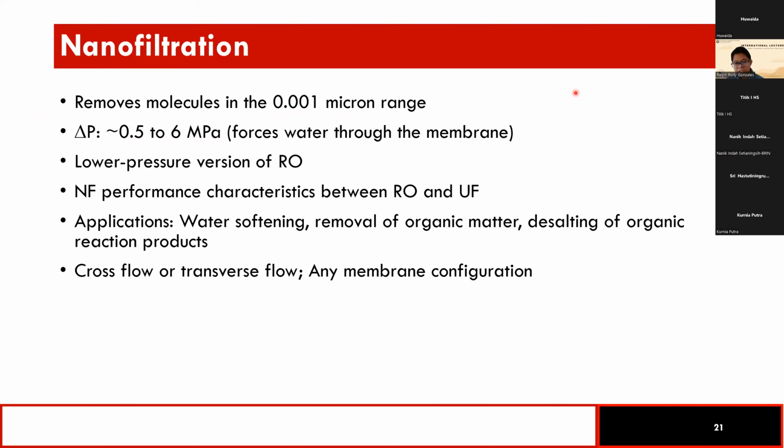So this is essentially considered as a lower pressure version of reverse osmosis. And its performance characteristics are between reverse osmosis and ultrafiltration. So this process is the most widely applied filtration process for many applications because it only involves low pressure. It can be applied for water softening, removal of organic matter, and desalting of organic reaction products.